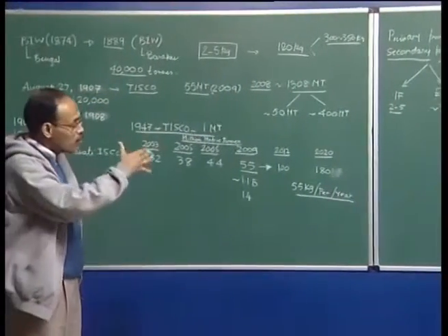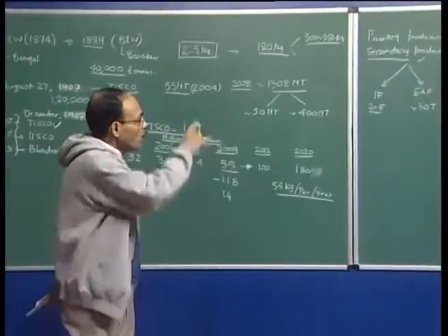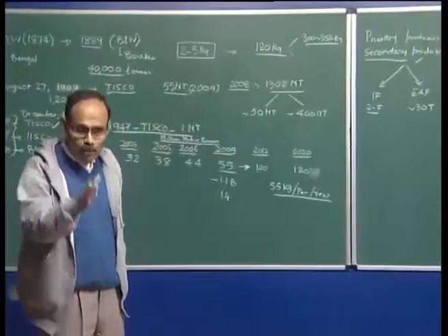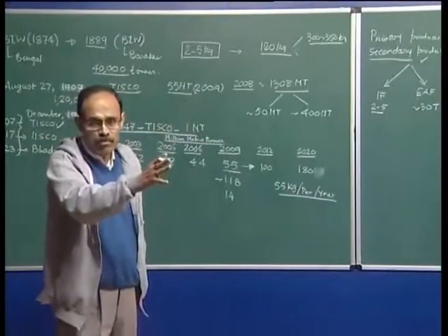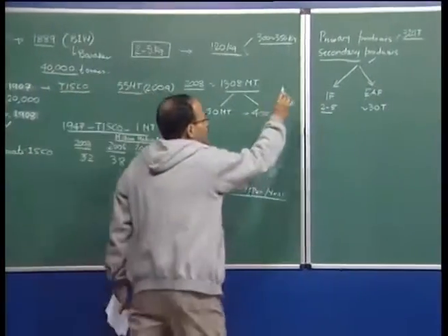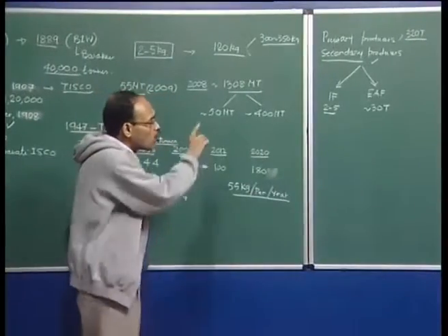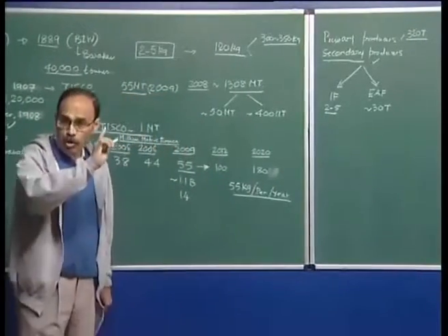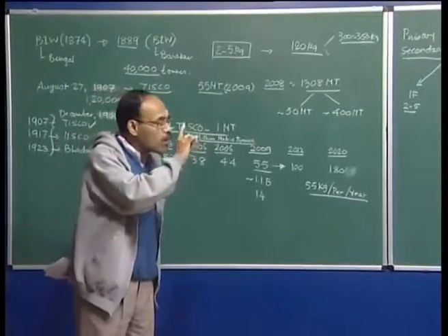We must understand that the raw materials are basically different. When you talk of primary producers, we are talking of integrated steel mills, with blast furnaces which produce molten metal or molten pig iron. On the other hand, when you are talking about secondary steel making, we are talking of induction furnace and EAF. There is no blast furnace. So the charge from which we are going to melt